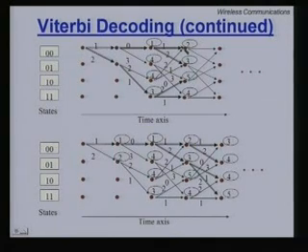right? And here we can safely retain that branch which has the lower branch metric, fine, and discard the other one, because passing through that node, only that branch would be optimal which is so far optimal, and we continue this exercise beyond and beyond. So, we only retain those many paths that correspond to those many nodes in a state, here only 4. So, the size of my memory which retains the number of paths does not increase exponentially, it is limited to the number of states.